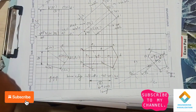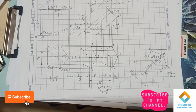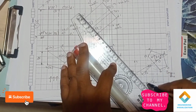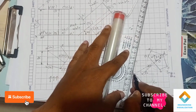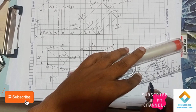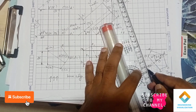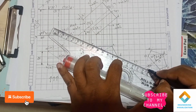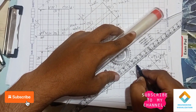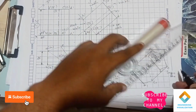So cut this arc, and finally we get A1 and B1. Now again construct the pentagon here. However it is in the second position top view, we need to maintain the same thing. Wherever there is a continuous line, we draw with a continuous line. Where there is a dashed line, we connect with a dashed line. So construct the pentagon here in the same way. Wherever there is a dashed line, we construct with a dashed line, and where there is a continuous line, we construct with a continuous line.